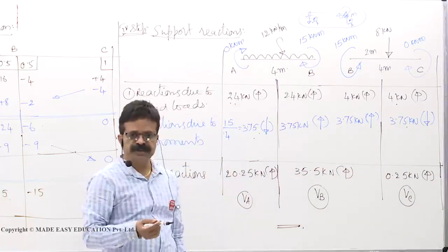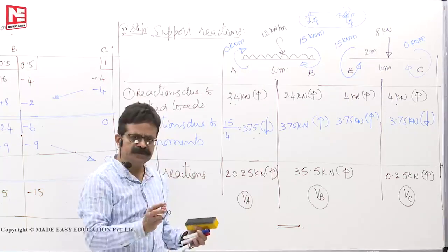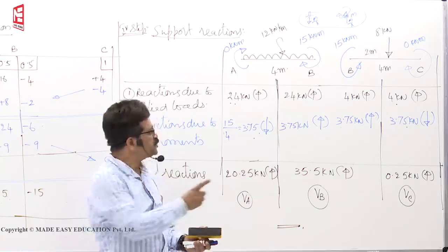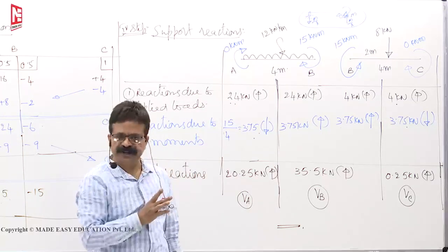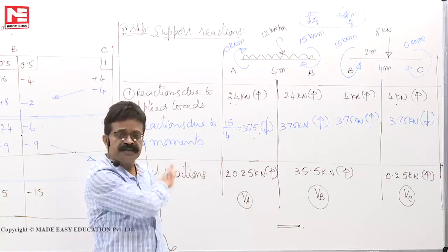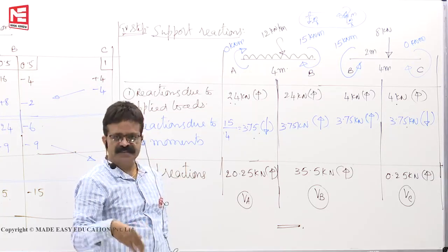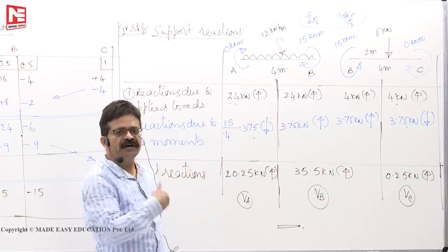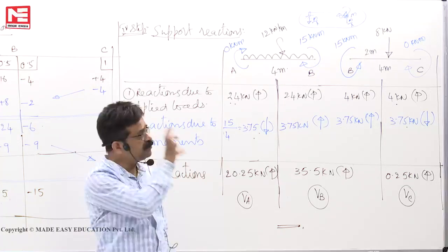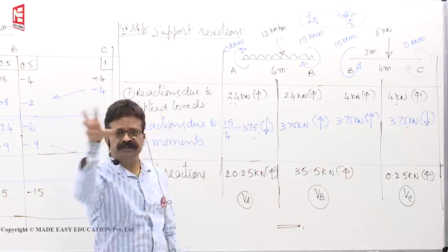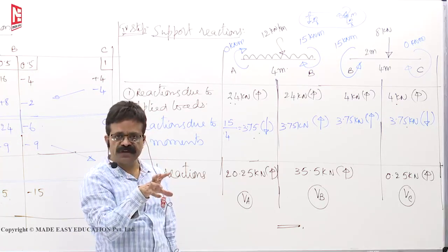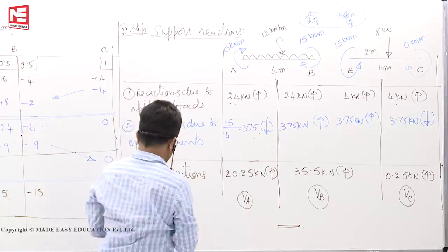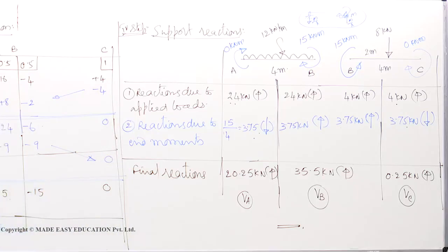So in any continuous beam, whether you use slope deflection method, moment distribution method or matrix methods, if you are asked to find the reactions, you must be able to draw this type of free body diagrams. We use such free body diagrams everywhere, whether you take plastic analysis in steel structures or SDM, slope deflection method, moment distribution method or matrix methods. We have to use them whether you take beam or frame. We must draw individual free body diagrams, find what individual loads, individual effects, reactions, then add them from the principle of superposition.